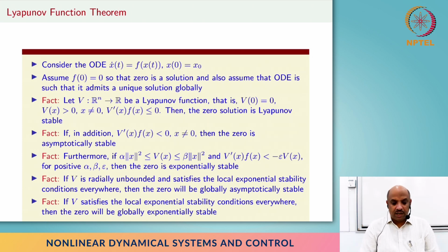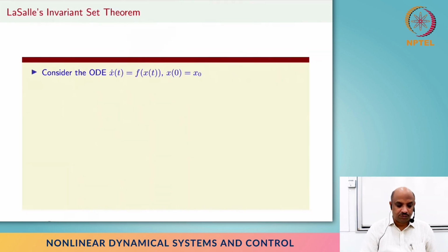So the nice thing about this method is, are you looking for Lyapunov functions in the dark? Absolutely not. The converse results of Lyapunov say that there always exist Lyapunov functions such that something is true, right? You don't have a converse necessarily for everything, but for exponential stability and asymptotic stability, one can actually have a converse theorem. But unfortunately, the converse theorem doesn't provide an algorithm to construct one, and that's the biggest difficulty we have with the Lyapunov function, right?